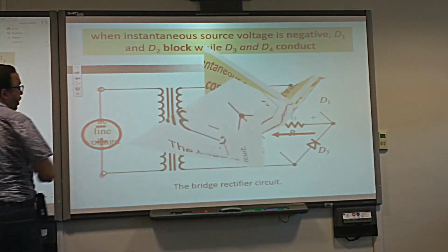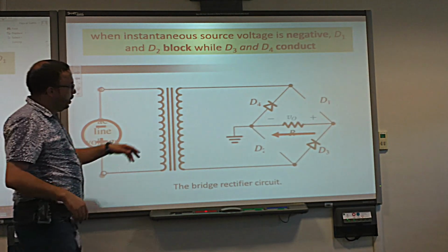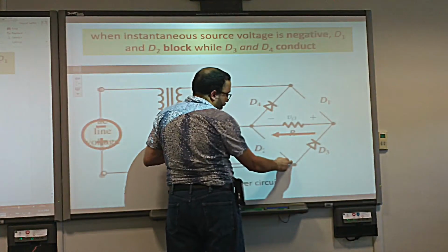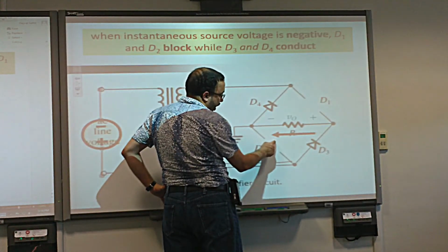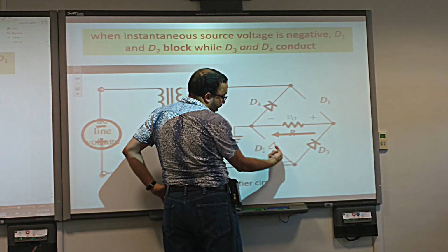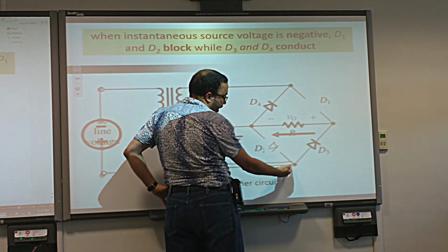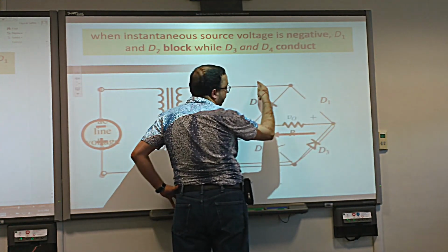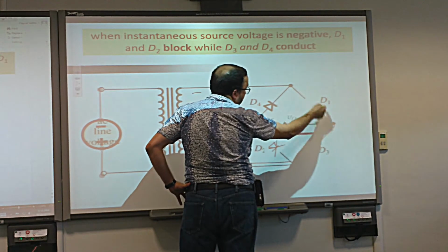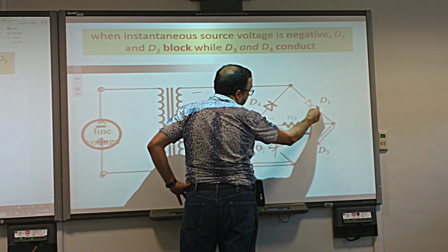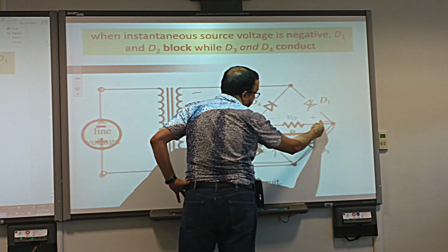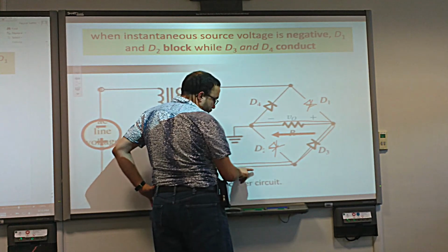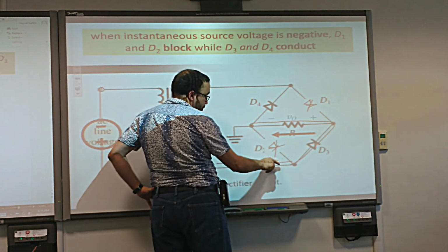The negative cycle is the other way. Now this is higher than this one. So now this voltage comes here. This diode was like this, yes or no? So now it's reverse bias, then this is ground, this is higher voltage, comes here, then bye-bye. I go this way, and I look: this is negative, and this is positive voltage. So this one is also off, so I tell it goodbye, go through the resistor, and I come here. I can go to the ground, or I can go to the negative pole, yes or no? I prefer to go to more negative.